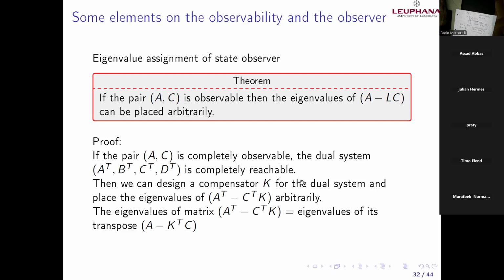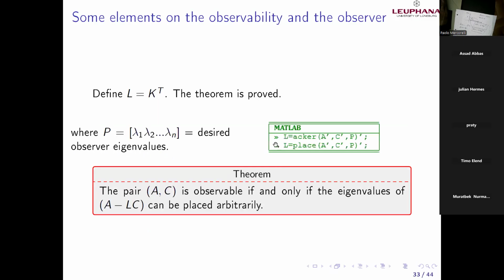We can see here the concept of reachability, completely reachable. I don't really have time to go in depth on this, but I will tell you a little bit with MATLAB, because we will look at one of these two commands or functions in particular, place. It's the same as acker, or place, acker in honor of Professor Ackermann.